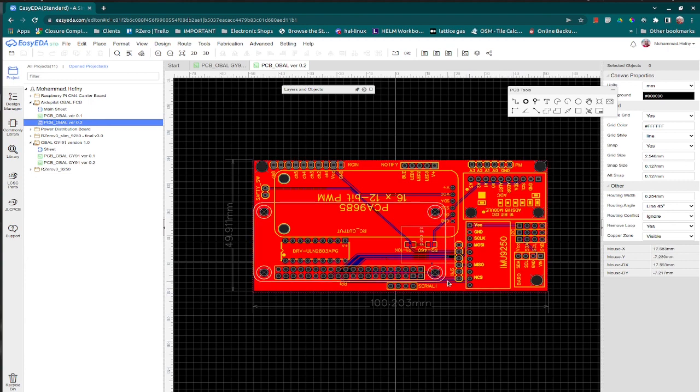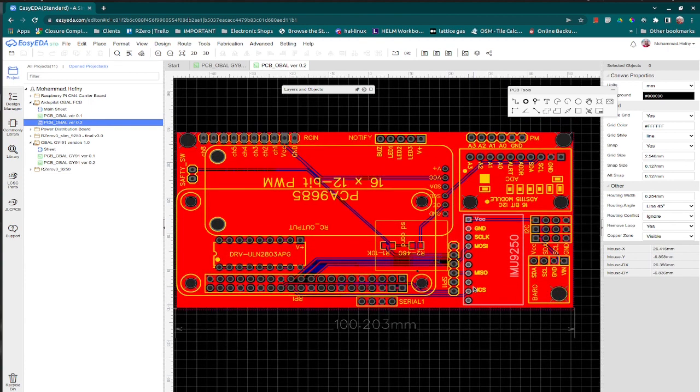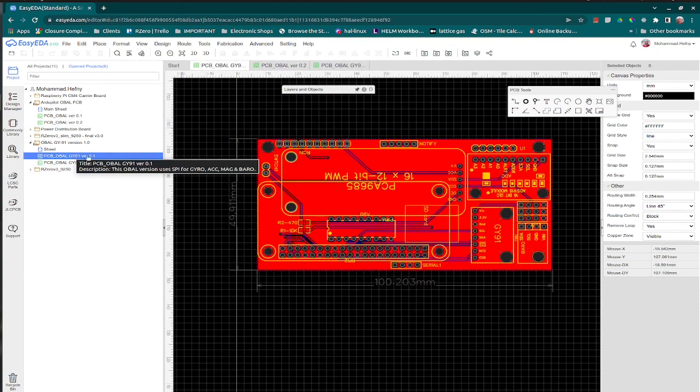As you can see here, this is the chip select line that is used to control the IMU, and the board already contains other pins for an SPI device, with SPI chip select one connected to it. The modification of the new board is here.